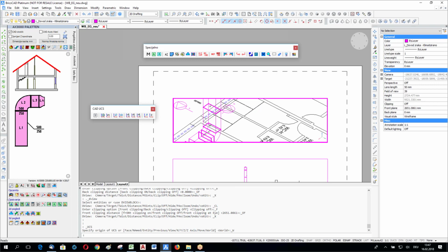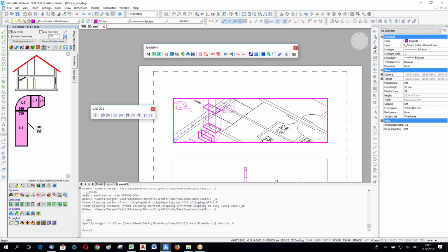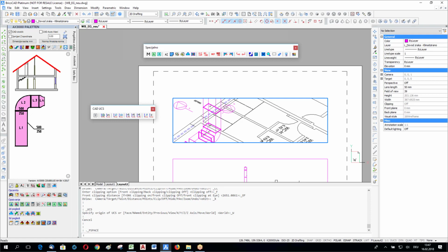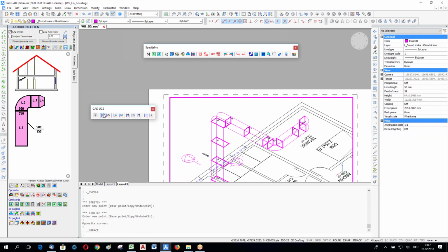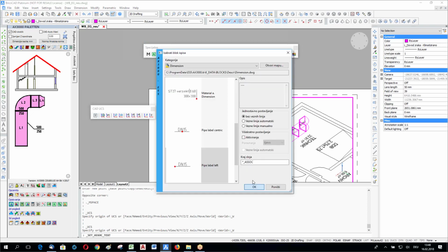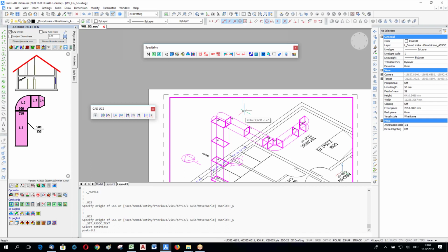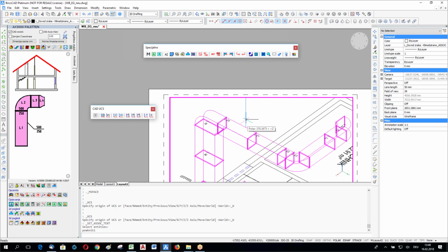It's easier when you're in the paper space, like this one, in every view, and you have world coordinates activated. It's a little bit easier. I explain it in a different way. If you're in a paper space and you have activated the world coordinates and you use the associated labeling, the associated labeling function is calculating an angle automatically. So you can see I'm in the isometric view. I have original world coordinates without any change, but the line starting at my drawing cross is going horizontally to the right. So the software is automatically calculating the angle to label.